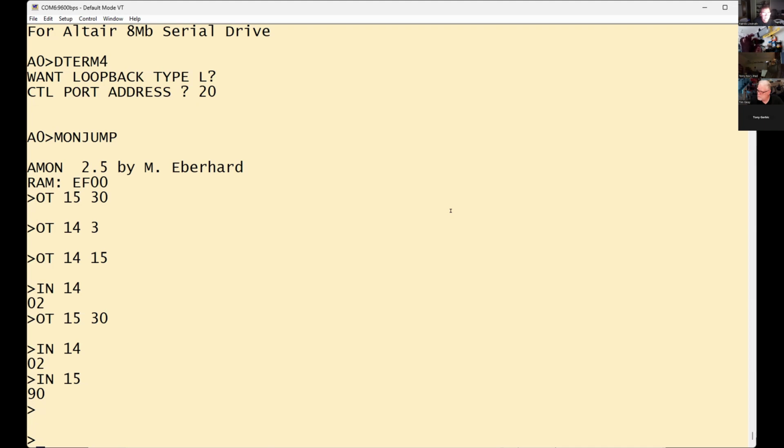Like if I put this little adapter in line. Well, see, here's the thing. What I'm seeing right now has nothing to do with your computer. Sort of, maybe. But like I say, the program works on the Altair, so all the hardware works on the Altair. There's two things happening right now. There's either a problem with that cable, or those jumpers are in the wrong place. I've replaced that cable from the 88-2SIO board to the back. I'm just running through the list. Either that cable's bad, or the jumpers are in the wrong place. Those should be pins 2 and 3, which I'm pretty sure it is. They're 2 and 3 according to the diagrams I have.